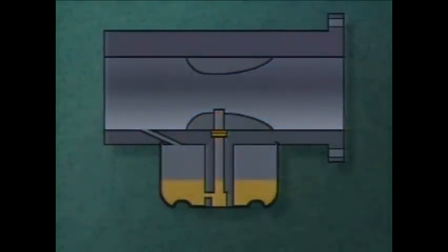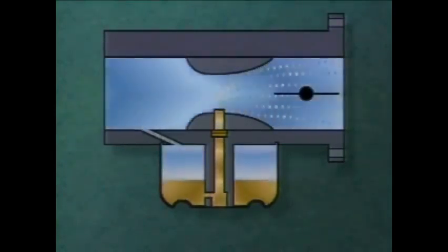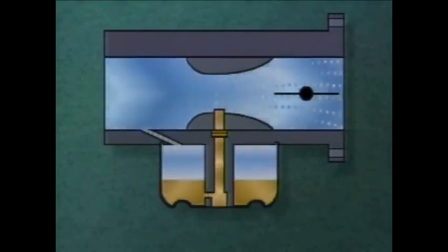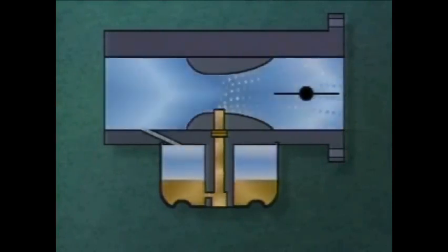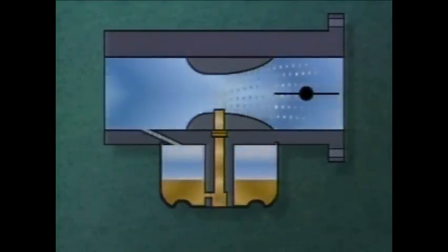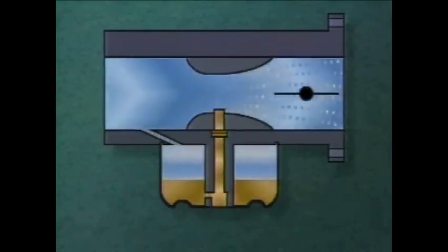Unfortunately, this carburetor allows the engine to run at one speed and one speed only, with no control over the amount of fuel that the engine is receiving. We can control the engine speed by adding a throttle plate to control the airflow. When the throttle plate is fully opened, it allows the maximum airflow, which increases the difference in pressure between the surrounding air and the air moving through the venturi.